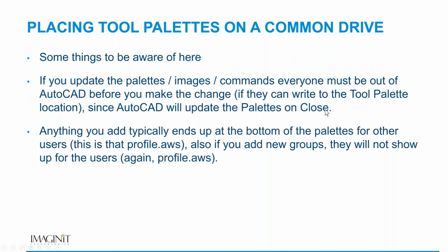That's a big one right there, is that what I see a lot of people doing is that they're making all of their changes to a live network location. Everyone has the option to read and write to that location. They make all their changes, they close AutoCAD, they reopen. Somebody closes AutoCAD after they've made changes and all of their stuff is lost. That's a big caveat I want to make sure everyone understands.